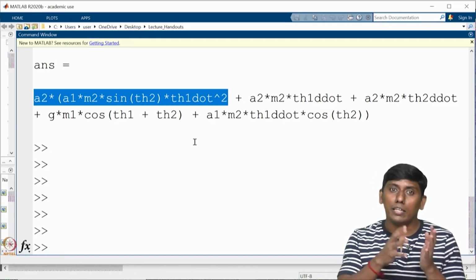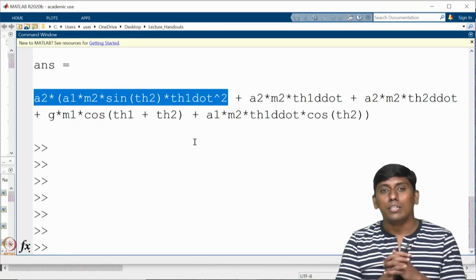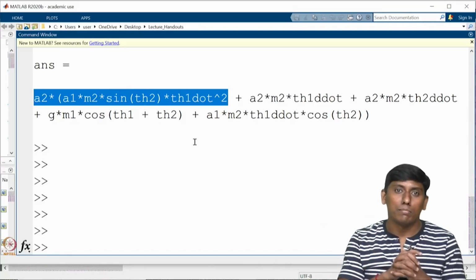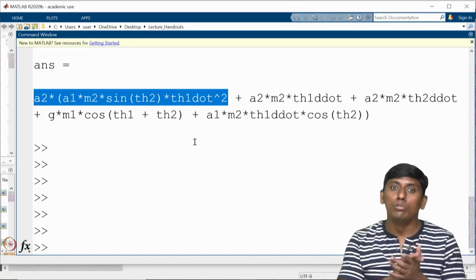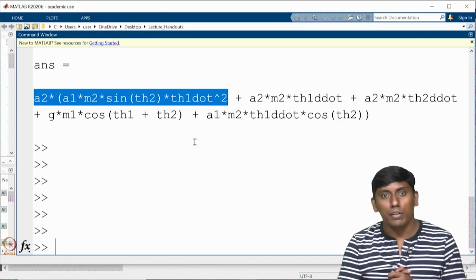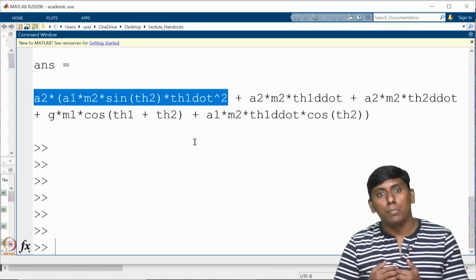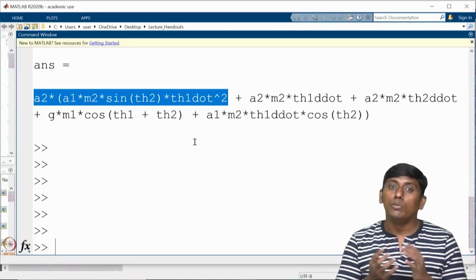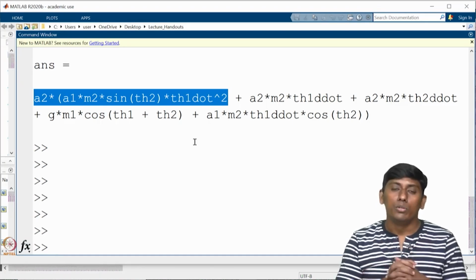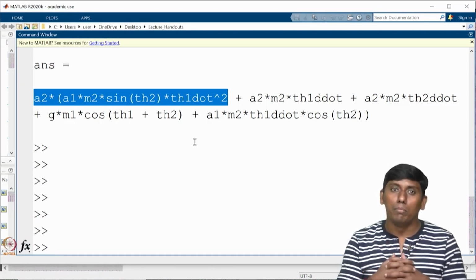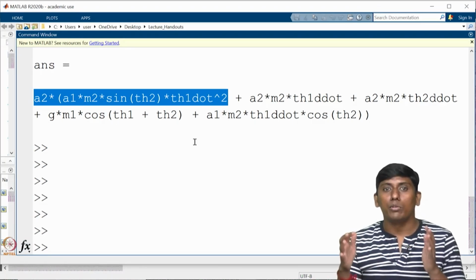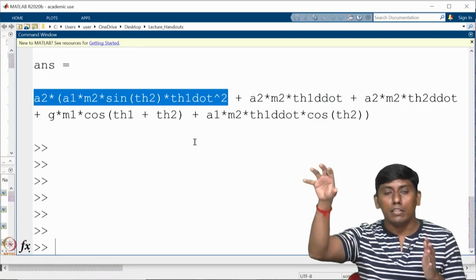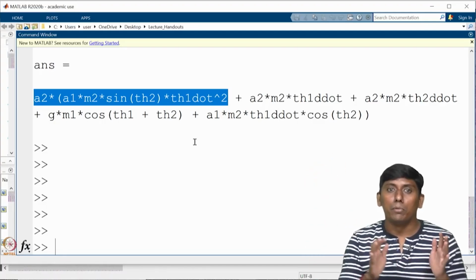In addition, it can give all three-axis forces and three-axis moments, which can be used for structural dynamics as well. Further, you can go up to the 0th joint or 0th frame and transfer what you can call the shaking force and moment. Based on that, you can say your end effector is taking this much load, so your base is supposed to be stronger.